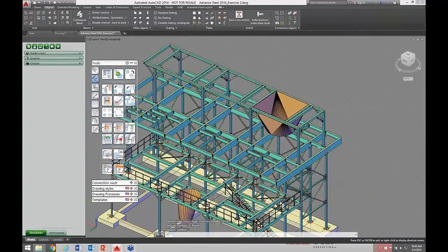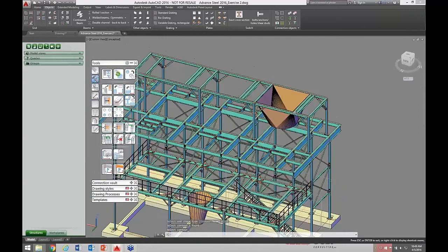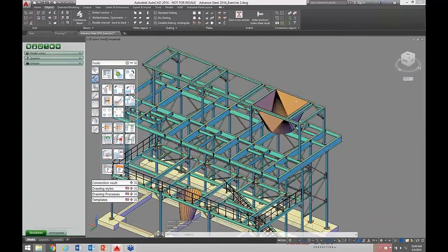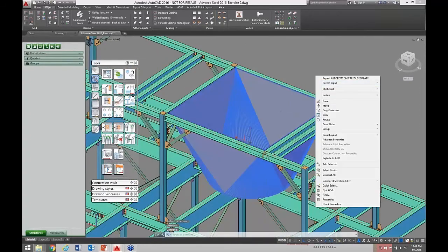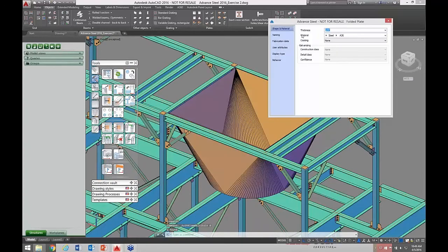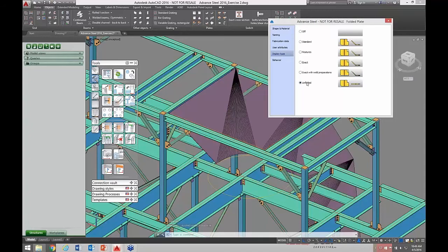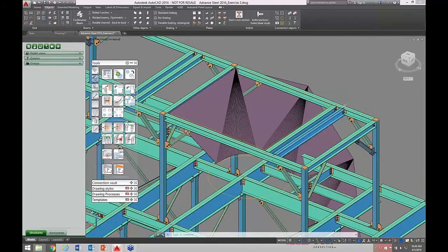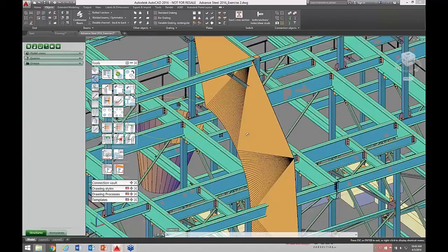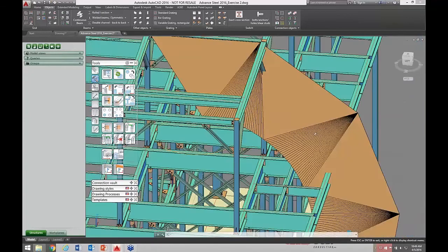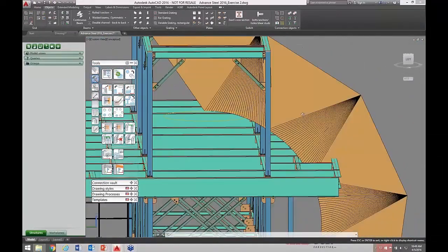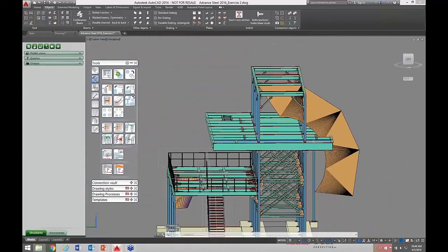And we get a nice transition piece here. Now, one of the benefits of being able to generate such a transition is that with its properties, I can actually unfold this. When we get into very unique conditions and we need to detail these items out, how advantageous is it to be able to unfold and detail out our part, our plate, and actually see these bend points, any cut transitions. And these are editable.